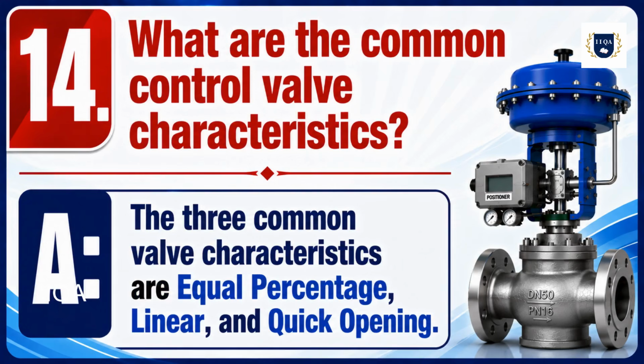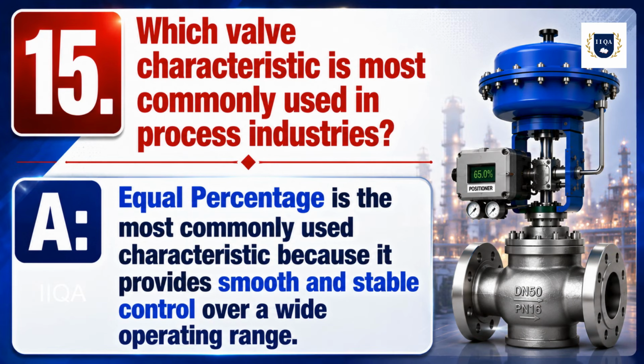14. What are the common control valve characteristics? The 3 common valve characteristics are equal percentage, linear, and quick opening. 15. Which valve characteristic is most commonly used in process industries? Equal percentage is the most commonly used characteristic because it provides smooth and stable control over a wide operating range.